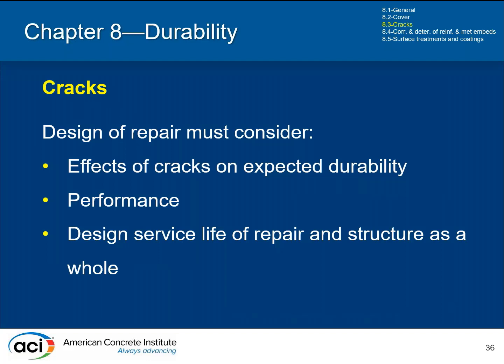So just to sum it up, the design of your repairs for your cracks needs to consider the effects of your cracks on your expected durability, its expected performance, what the expectation is for the structure as well. If you're repairing something where we need to limp it along a little bit, but in 5 years we're going to be demoing it and building up the latest and greatest, that may be a different repair approach than one like, hey, I have the structure, I'm going to be owning it for the next 50 years. You need to try to get me as close as you can to that level as well.